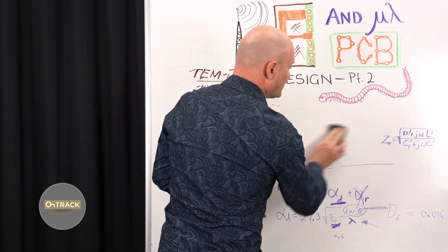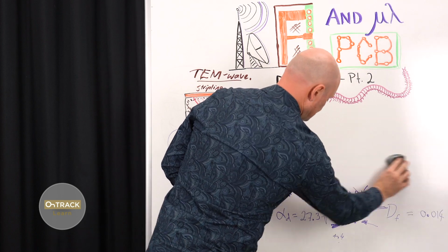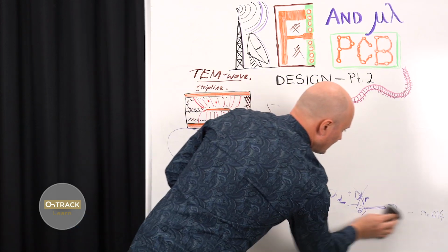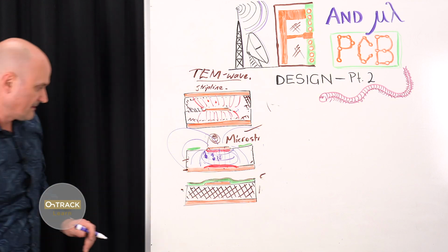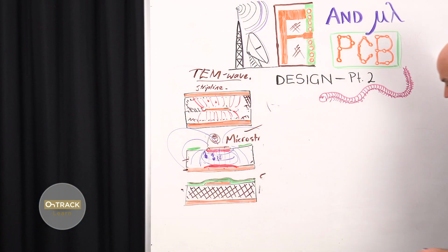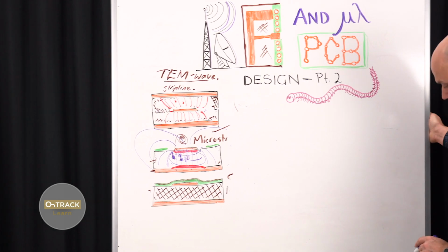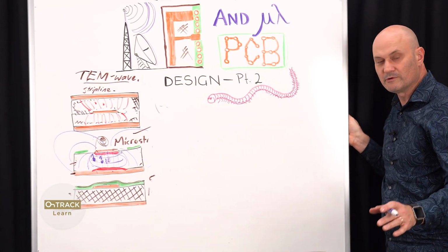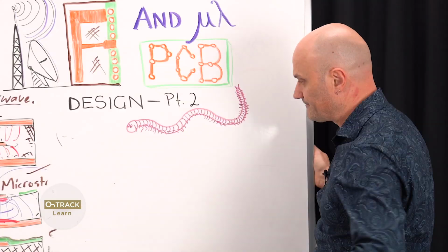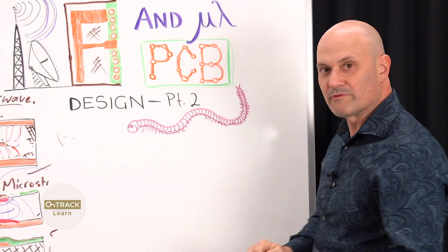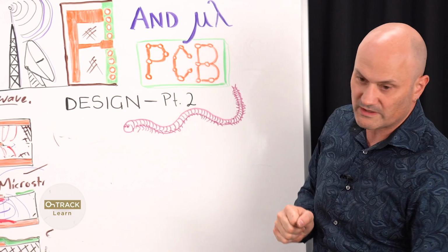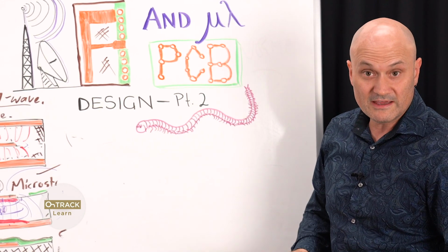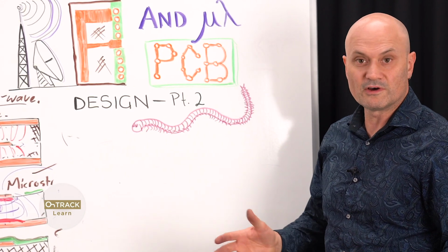We'll come back to impedance in just a bit. Let's say I have FR4 with those characteristics. What's my loss going to be? Let's say, so I run this through an actual calculator, one of the free calculators available that uses the formulas from the IPC 2252 standard, so they're pretty well tested over time and reliable.